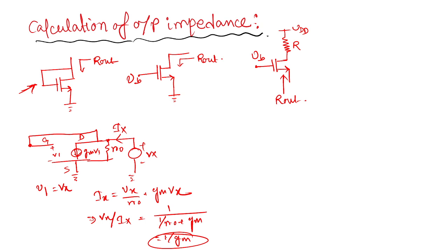Okay, now in this structure I am trying to solve intuitively. For AC analysis, this terminal becomes 0. Here, if you connect Vx and Ix, suppose R0 is present. You can see the value of VGS is 0 because the gate and source terminals are both connected to the ground, so no current flows through this transistor.